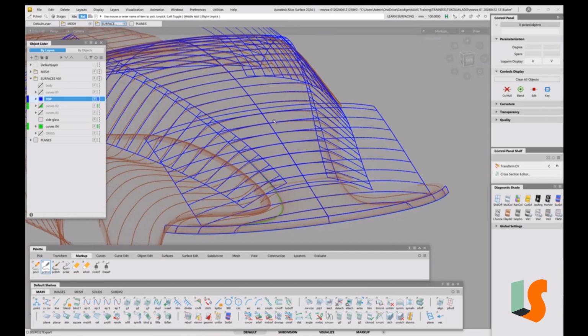But I prefer to overlap them so I can see where each of these surfaces is heading. Because if we then trim convert those back to another point, we'll end up with a super smooth pair of surfaces which almost join up without you having to even align them.